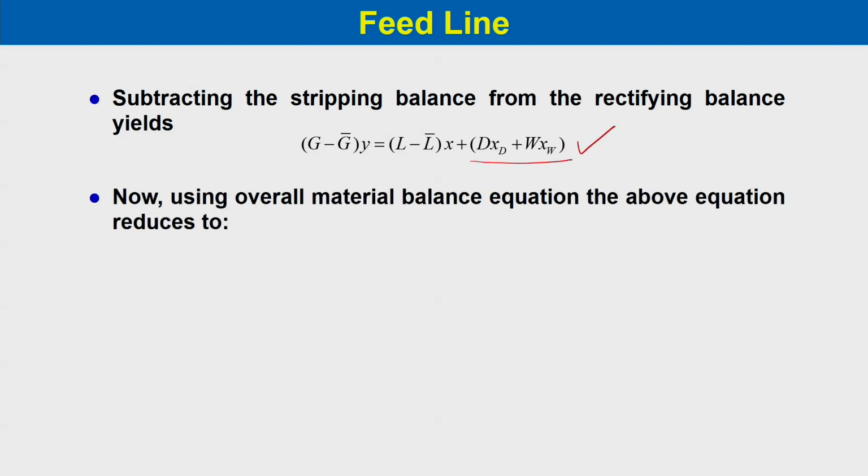Now, if we do the overall material balance over the whole fractionator, the above equations will reduce to (G minus G bar) into y would be equal to (L minus L bar) into x plus F into zF.